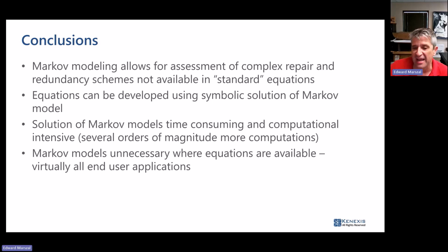At the end of the day, there is an equation that's going to be based on the logic and integration of that logic over a time series to come up with probability of failure on demand, average probability of failure on demand. So it really doesn't matter what graphical tool you use to demonstrate what your logic is. They should all give you the same logic. And then it's just a matter of solving that logic or simplifying that logic into an equation.